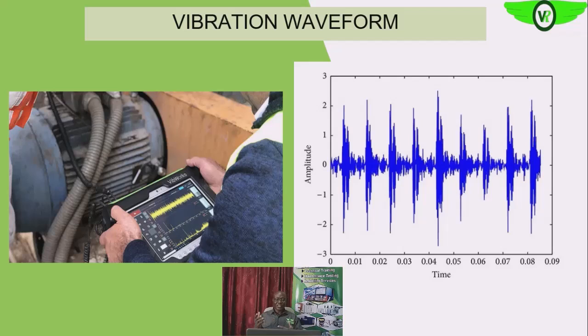Once it's increasing, you know something is developing within the electric motor. Are we getting it? But the drawback is that before it shows up in that increase, it may have gone far into the PF region of your bathtub curve,